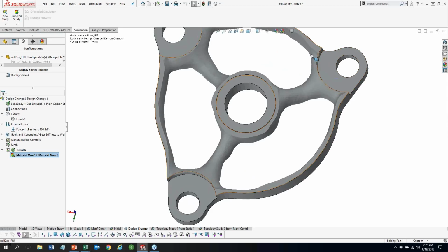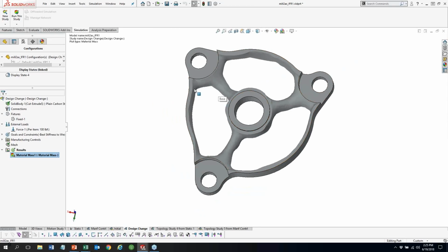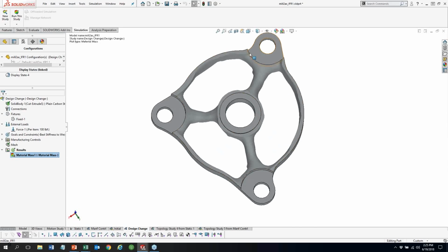With this step down here, it has created some walls in this area, and you can see these cutouts are much more rounded, which is most suitable for a CNC machine. So when you have a part like this that we've retained the outer shape, and all we have to do now is just remove these areas, it's as easy as sketching them in and using extrude cut, right?